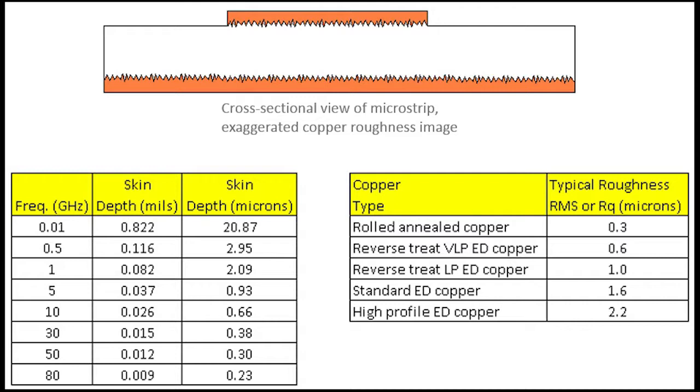So for insertion loss, what I'm interested in is the copper surface roughness, and specifically the copper surface roughness that is shown in the drawing here, where I've shown a microsection view of a microstrip transmission line circuit, and at the interface of the substrate and copper, that interface is what I'm talking about for the copper surface roughness. And it's that interface that is more problematic. If the copper is rough, it will actually slow the phase velocity and also will increase the conductor losses.